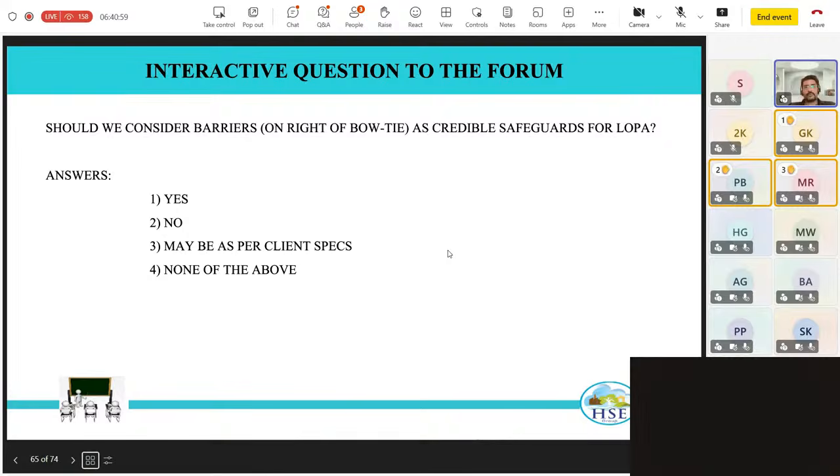Like they would predominantly configure a fire and gas detection system only to provide audio and visual hooters and alarms, audiovisual hooters at the local site and alarms in the DCS or PLC room. So what they are doing is they are just using this mitigative safeguard, which is the fire and gas detection, to only alert the operator or people in the vicinity or the community to evacuate and go to the assembly point.